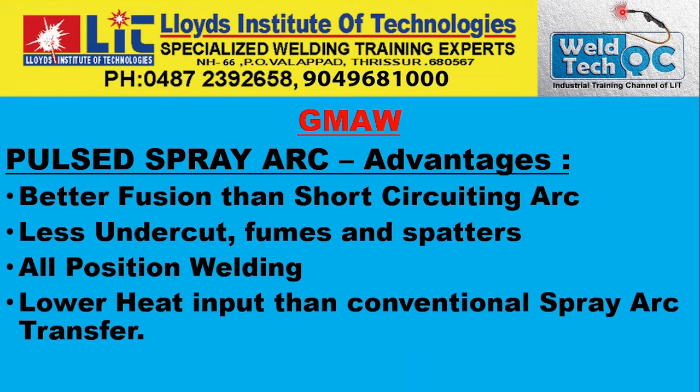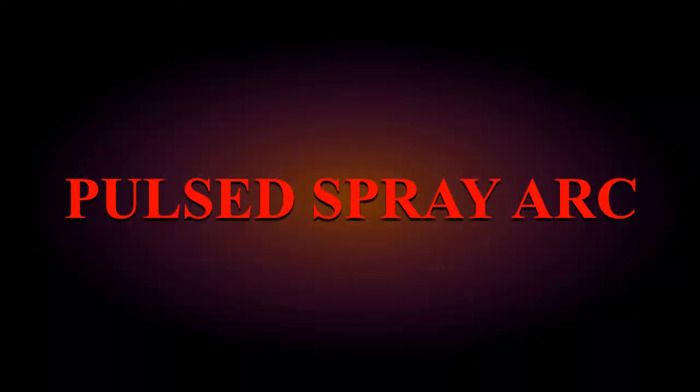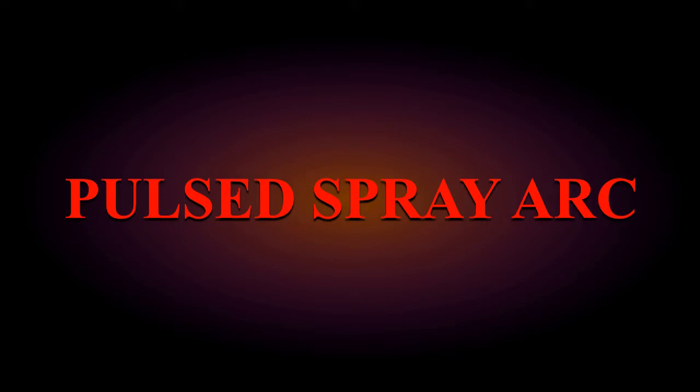Let us see the advantages of pulse spray arc. You get much better fusion than short circuiting arc. You get better arc control, and your undercut, fumes and spatters are minimal. You can weld in all positions using this modified metal transfer mode, that is pulse spray transfer.